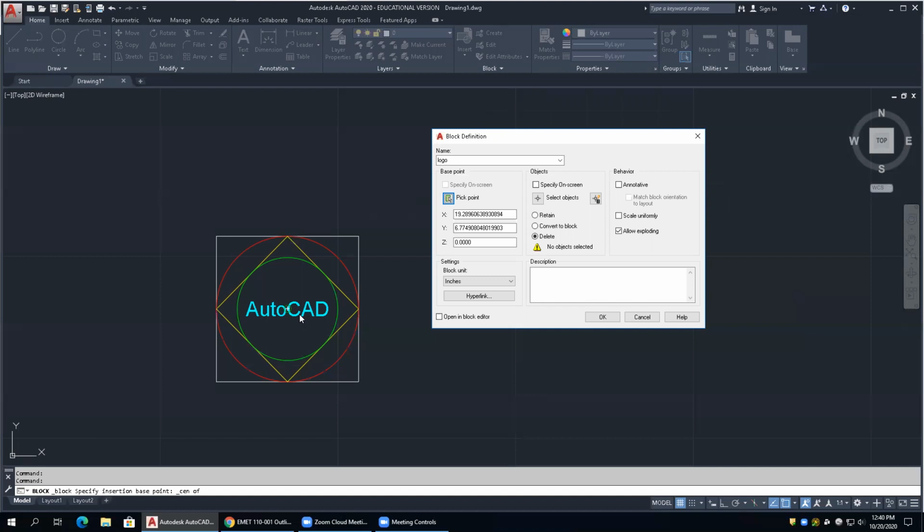Okay? So the next thing that's very important is to select the objects that you want to make the block out of. Now, if you're going to have attributes on this block, if you guys ever want to experiment with that, you have to create the attribute definitions before you create the block. You can, I think, add them now, but it used to be pretty difficult. It's really hard to add things sometimes, okay? So you kind of want to get it right the first time.